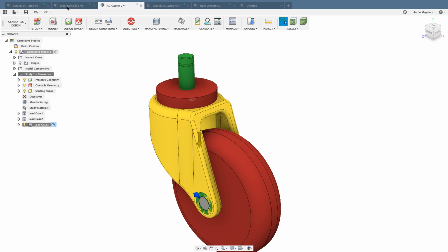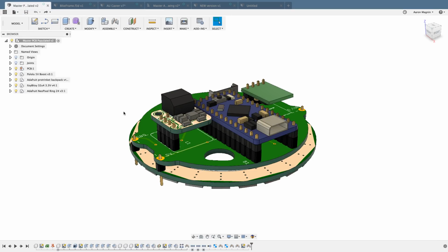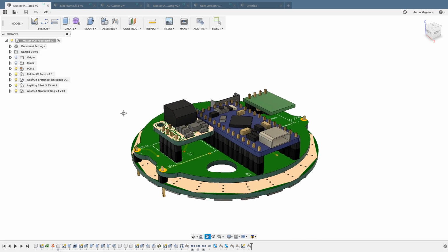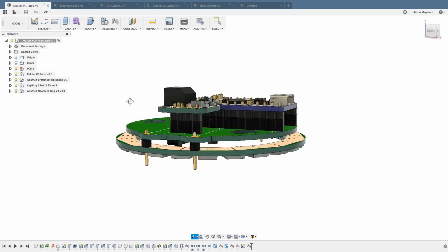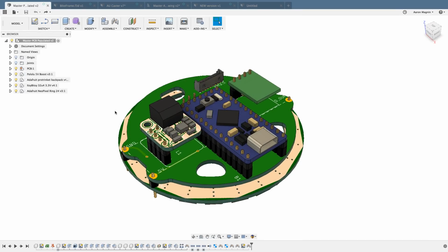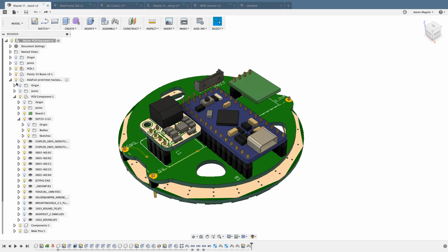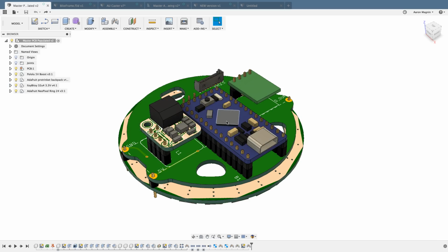That said, let's jump back into another model, and in this case, this is a circuit board from this air quality sensor that we use at the factory at AU. So you actually had an opportunity to build one of these yourself, but this is one of these cases where there's multiple levels of components, and it just goes down and down and down. And so if you find a case where you select a face, like I've done here, I just left clicked it once. If I hit V, I've hidden that body, and I have really no clue where it is.